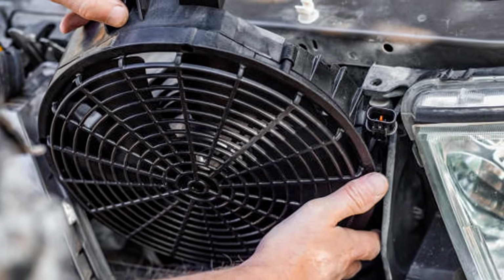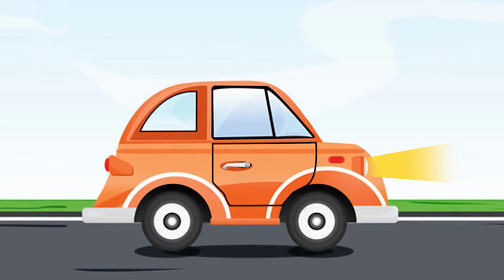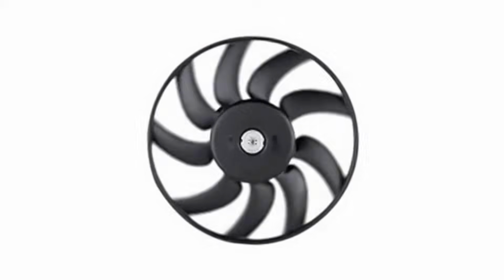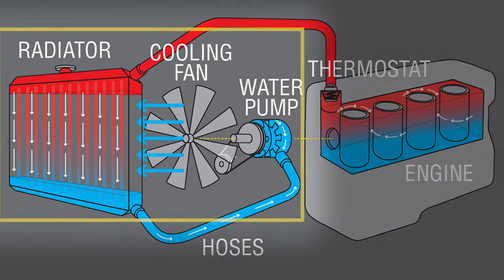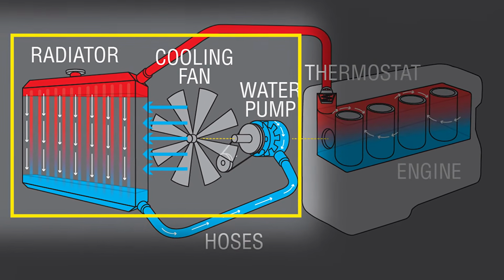Now, one thing to mention when it comes to overheating: when you do have an issue with the electric cooling fan, it is pretty uncommon for the engine to actually overheat unless you're idling or traveling at very, very slow speeds. It's because in these situations, you don't have enough air coming over the surface of the radiator on its own, and so that's where the cooling fan is essential for turning on and providing that additional fresh airflow over the radiator to help keep the coolant temperatures in check.